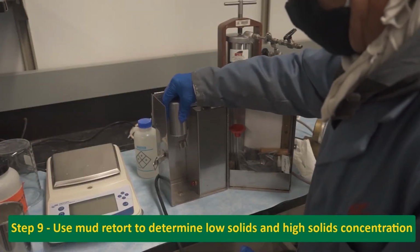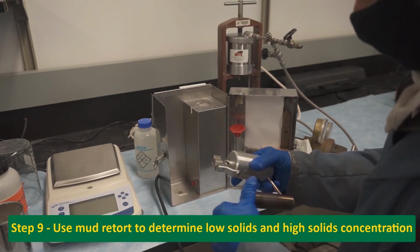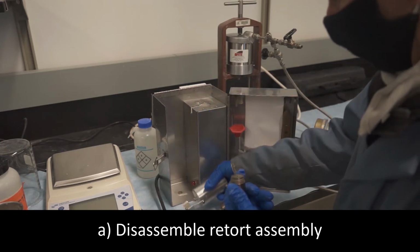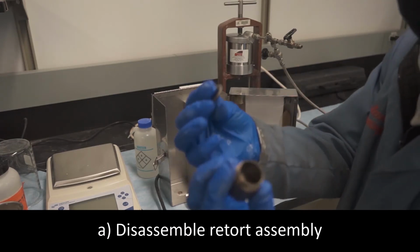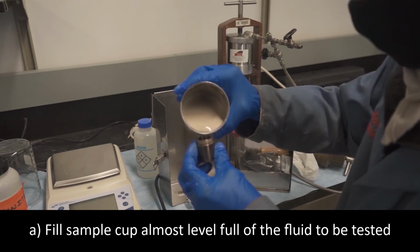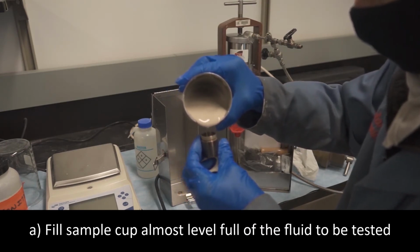Use the mud retort to determine the low solids and high solids concentration. Apply the following procedure. A. Disassemble retort assembly. Fill sample cup almost level full of fluid to be tested.